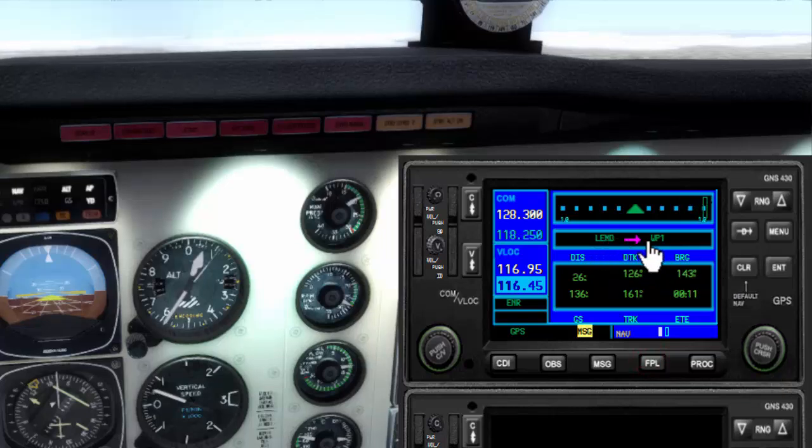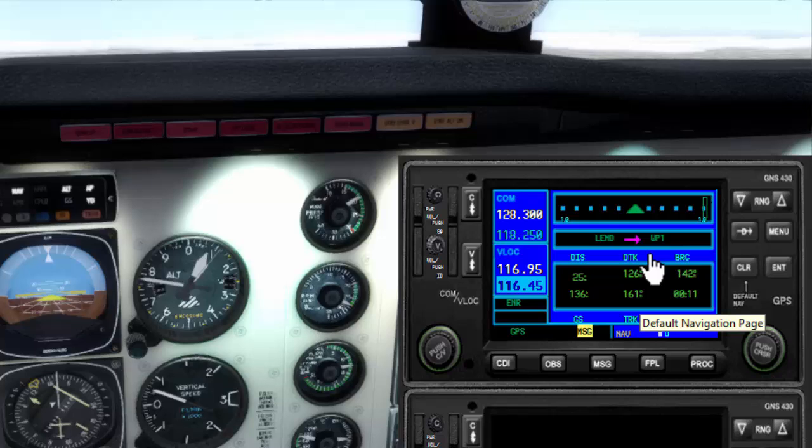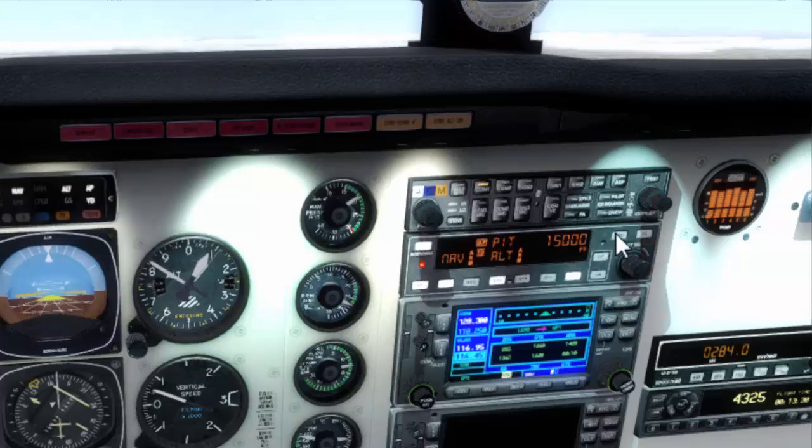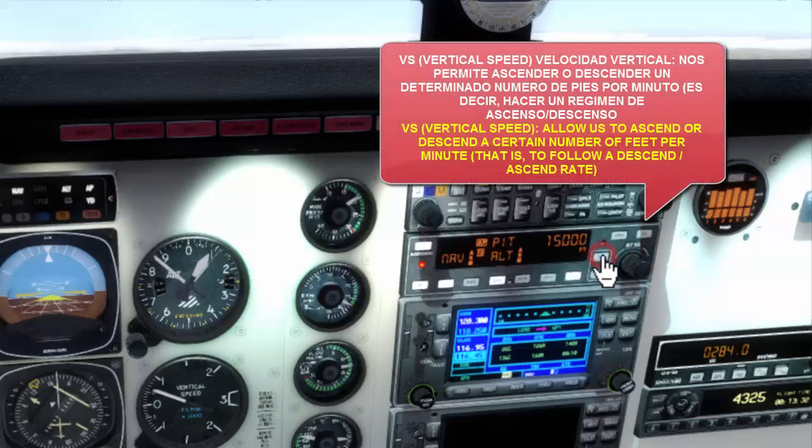And remember that we are going from Madrid Barajas to waypoint 1, which will be the first point of our flight plan. And right now the behavior of the flight director or the course director indicator will change. In this case, the arrow is broken because we have not reached our flight plan yet. But when we reach our flight plan, the yellow line will be complete, okay?